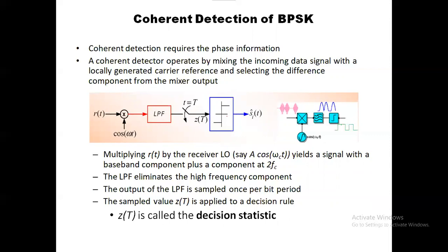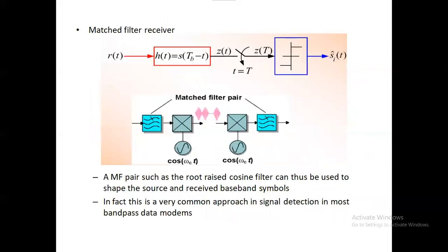We are using the same technique we adopted in binary ASK. Also, the modulation and demodulation are followed by the matched filter pair, which is designed over a specific pulse shape, or we may also call it the pulse shaping filter.